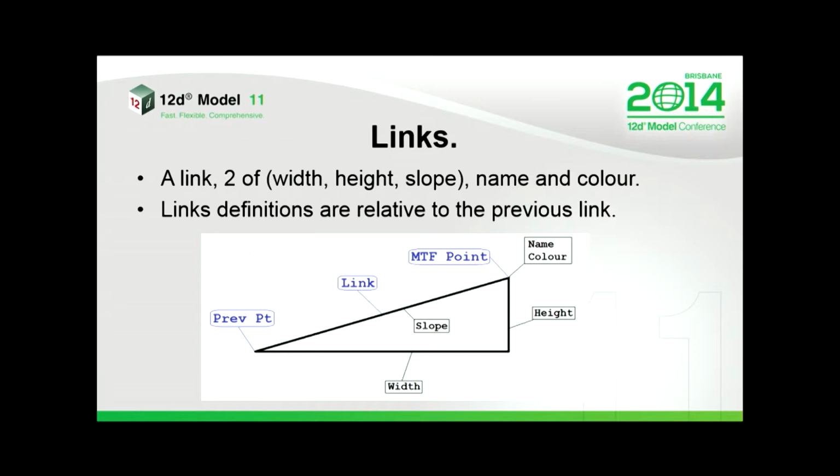It's a link. And the other very clear thing to remember with links is that they are completely relative to the previous link. Remember, even when you use something like the insert absolute modifier, it might have been inserted to a link that was 3 or 4 previous relative to it, but at the end of the day it's resolved back to relative. It's not that big number, it's the little number. And it's very important to remember that if you do any modification on any link inside, everything on the outside would be pushed out relative. It's just one of those little concepts that must be absolutely clear.